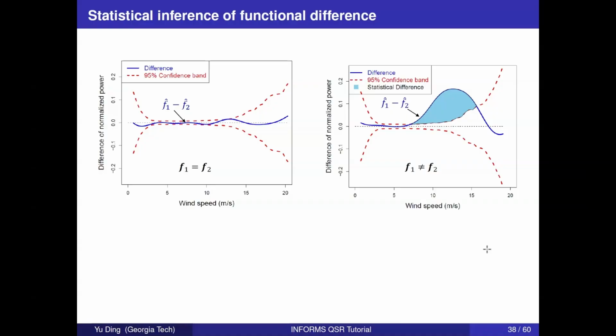And the area right before that rated power is the steepest part of the power curve increase, which, if you change that steep part, will give you the maximum benefit of modifying the power curve function. So this more or less confirms that whatever they did on that turbine really delivers on the promise they intended. Okay,